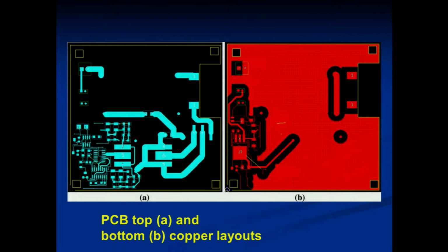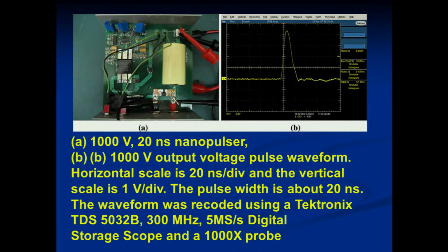We use it, the capacitor was like in farads, we normally use microfarads, so farads means, okay. So this is a 3000 volts capacitor, okay. And then the MOSFET, again we use ISEX, I have the report, so we can do that. Again you see it is not perfect, but this is good enough for all practical purposes. So you have a 1000 volt output pulse waveform, you have the scaling and all. So basically we got almost the desired values, okay, 25 nanosecond, and then the shape is not good, but we are happy with that, okay.